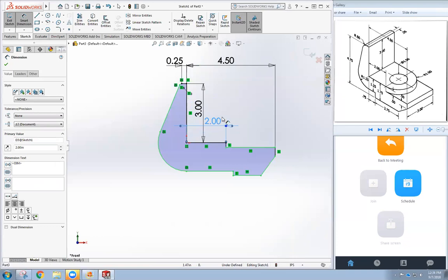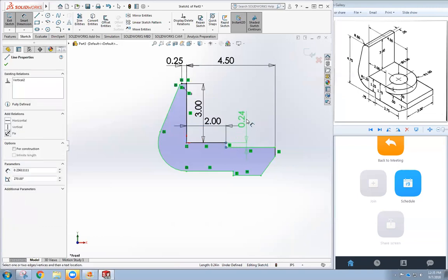Oh, maybe I should talk for a second about how I got this 2 inches. I can see from the sketch that I'll go from this line to the center of my circle, which is 2 inches. So I'll create this dimension here because that's where my rectangle will be. We'll go from the top view in a minute to create that arc and the hole that goes through the part. But for now, that's how you came to the 2 inch dimension.